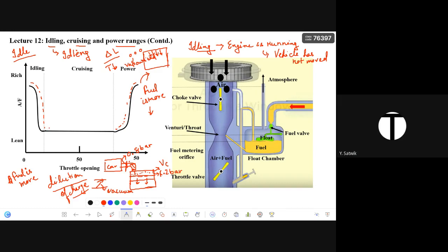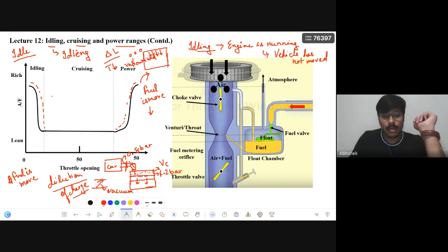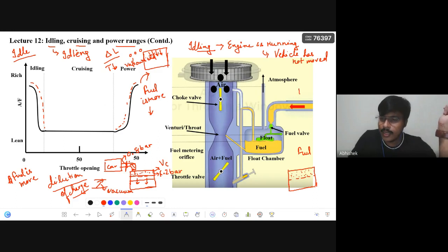No, sir. Please explain again. Okay. So generally what is happening in high power is that we are supplying richer mixture. Now why is this so? Because all the fuel that is coming through the carburetor, some might be in the liquid form. Everything might not be getting vaporized or atomized. There might be some fuel which is in liquid form. And when it is liquid form and there is certain temperature or certain heat, this liquid will get vaporized.